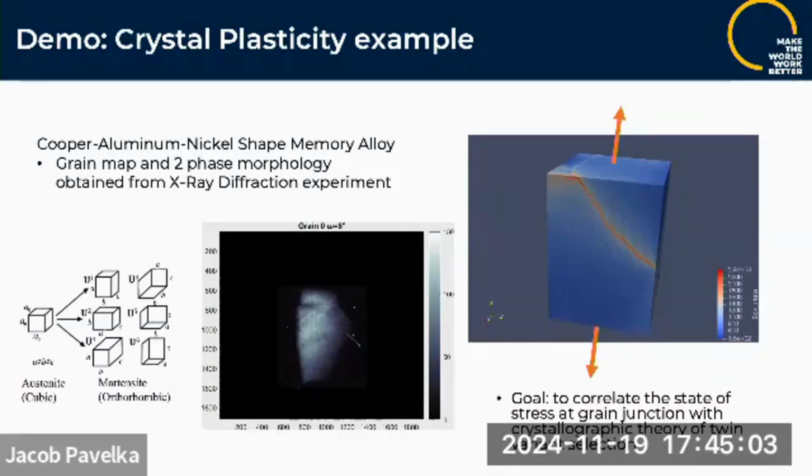So this is one grain, and there is one crystal phase that shines up very brightly and one that is totally dark. You can see in some orientations, like right now, these bands going across. That is another crystal phase that the material is shearing into to accommodate the strain imposed on the material.